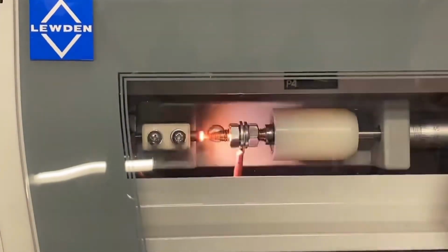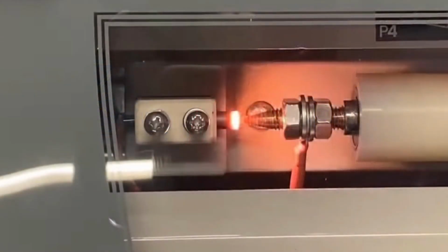This situation can then be intensified by the arc carbonising the PVC insulation around the conductor, which can then start to generate some serious heat. In tests at the Lewden factory, the carbon rod used to simulate the PVC insulation reached 200 degrees Celsius, and it's not unheard of for arc faults to generate temperatures of 6,000 degrees Celsius. As you can imagine, this could very easily lead us to a situation where this could start a fire, leading